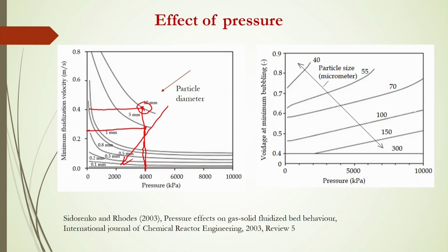As for the pressure effects on gas-solid fluidized bed behavior, from this fluidization behavior we can observe what the minimum fluidization velocity should be at different pressures, and also what the voidage should be.